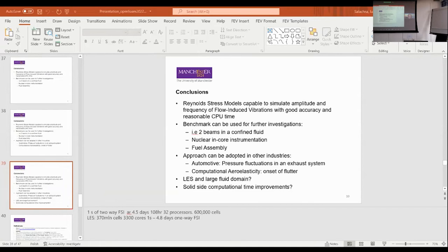Maybe the short answer is no, but maybe you can trick it using a manual decomposition where you just split it on 32 cores and you tell the other 9,000 or whatever cores you have left that they have no cells. So decompose... Okay. I think it will work with that if you make a manual cell decomposition. I've done that where I've run it in serial, where you trick it to put all the cells on one processor and then it runs in serial. So I think you can do that. Or you'll get a segmentation fault when you do that. I'm not sure. So. Okay, yeah, thank you.